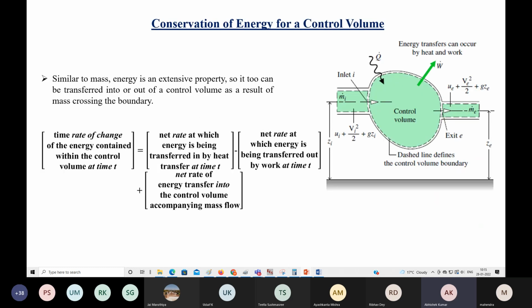Now, what we have seen, we have solved the conservation equation. Mass of accumulation inside the control volume equals all the mass inlets minus all the mass outlets. If dm by dt of the control volume equals 0, that is the steady state. In that case, all mass inlets equal all mass outlets, which we derived in our previous case. So that is the conservation of mass equation.